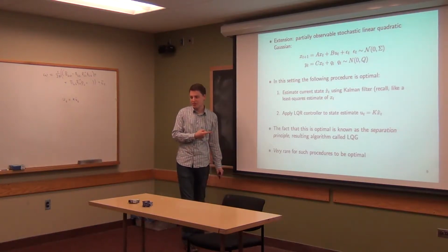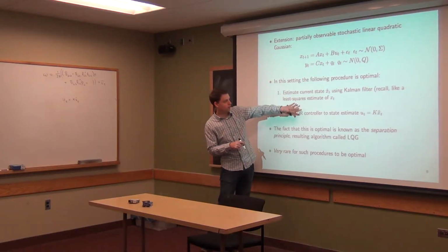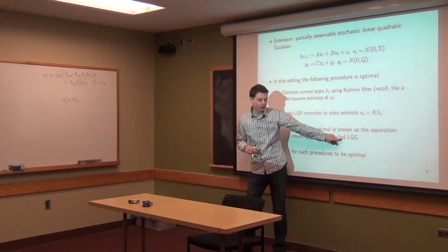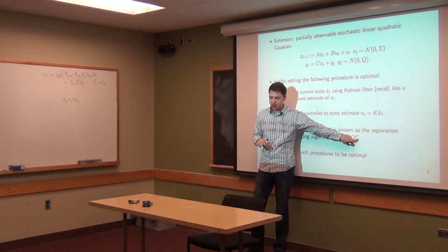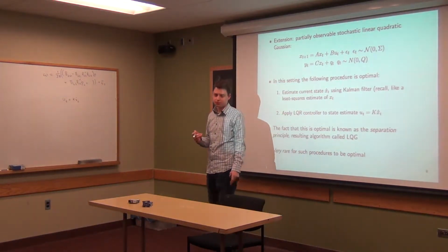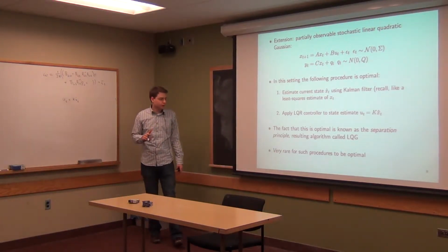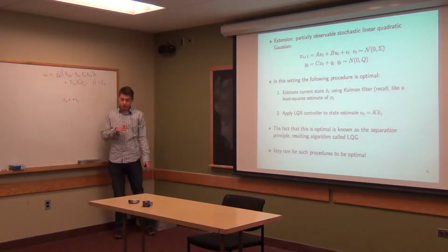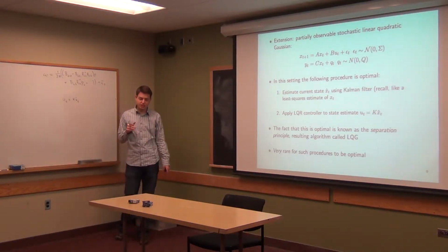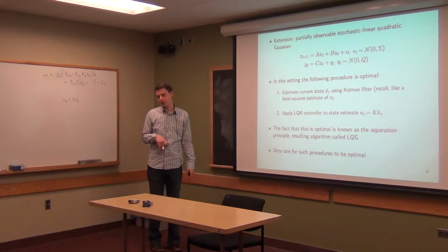And I think this is about the only setting where this separation principle actually holds. There's also this algorithm where you use a Kalman filter and LQR, called LQG. So you may see that acronym. It's just LQR with a Kalman filter. But again, it's the best thing to do here, but it's extremely rare that it actually is the best thing to do. Not very common at all.